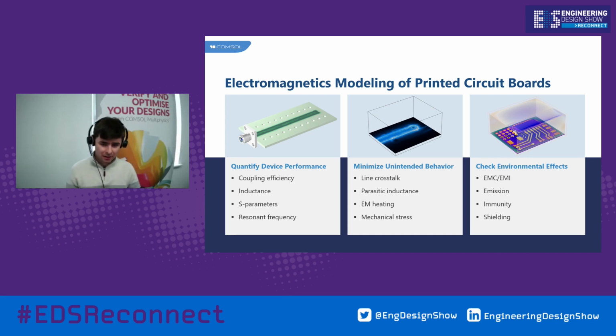So this is essentially working out or making sure that the device works in the way that we intend it to. So this might be looking at things like the coupling efficiency between different parts, signals on different parts of the PCB, maybe inductances of tracks on the PCB, or S parameters or resonances if you're thinking more in the RF regime. The second and equally important thing we might want to do is to minimize any unintended behavior.